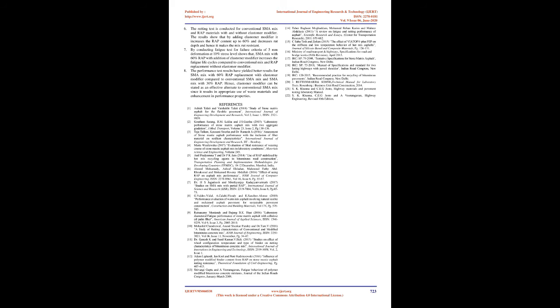From the results obtained it is observed that the failure criteria for 5 mm deformation at 10% stress level shows that 60% wrap with the addition of Elastomer Modifier in SMA mix increases the fatigue life cycles compared to conventional mix and optimum wrap without Elastomer Modifier.